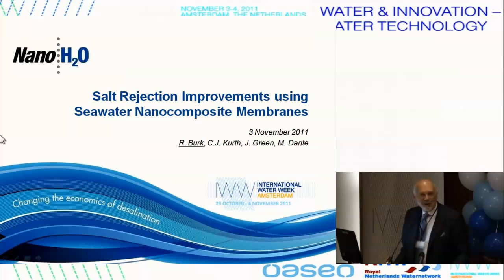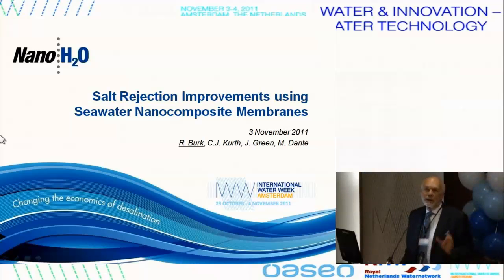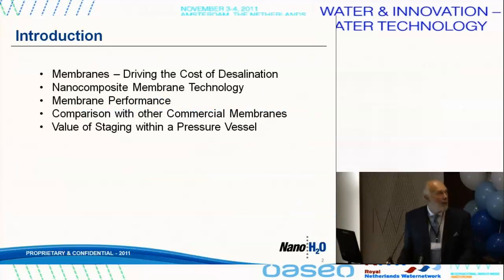Thank you very much for the introduction, and thank you for inviting me to this conference. All right, got it. So anyway, I want to talk to you about salt rejection improvements on seawater nanocomposite membranes. These are reverse osmosis membranes, okay, and there is some confusion sometimes because we use the term nano, and there are also nanofiltration membranes, but these are actually conventional reverse osmosis membranes.